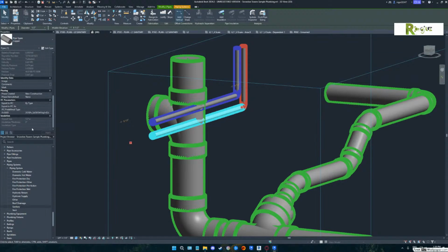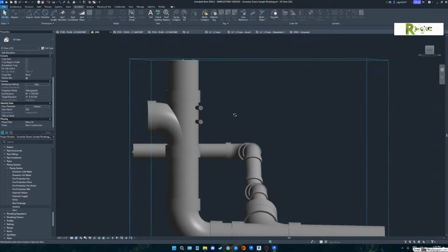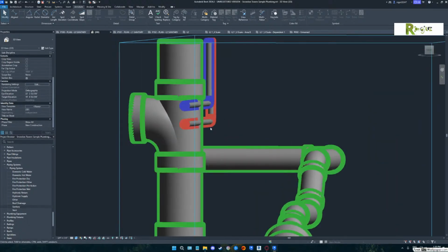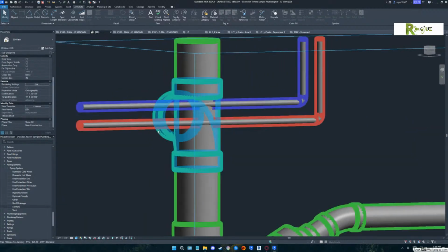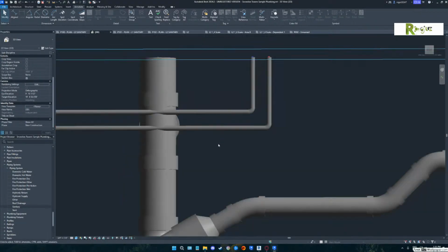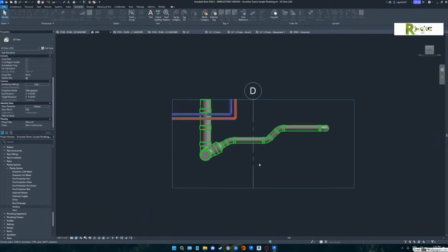That's a typical problem, Nathan. That's a typical problem that you're going to get with a file, is that they don't run that insulation on there. Therefore, they're not thinking about where things are going to actually exist, because insulation's only going to make that problem that much worse. Well, you're actually going to find that the red's going to even run into the blue. You can't put two pipes as close together as they've drawn that. Okay. All right. Just trying to show you how I feel my way through a set of drawings.